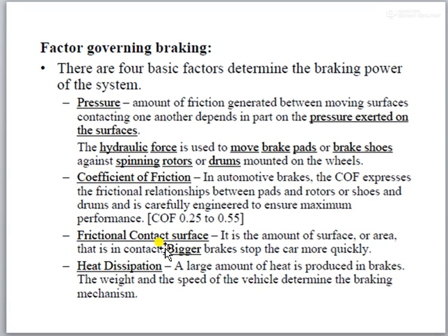Okay, in case of the drum brake, that is a thing which is used. So these are the four parameters which govern the braking effect or braking efficiency. That is pressure, coefficient of friction, frictional contact surfaces, and the heat dissipation rate.